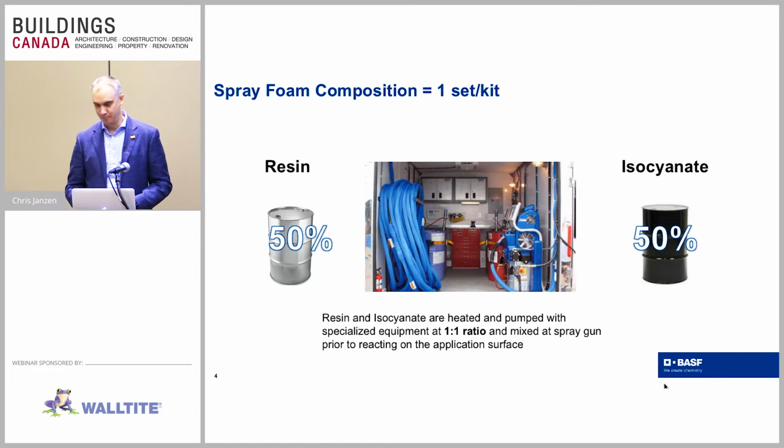So, you see every now and then on YouTube, the drill and fill applications where they drill holes into the drywall, put their spray foam gun in there and pull the trigger. You don't want to do that. It's not advisable. It's actually not recognized in the building code because it can't be inspected.